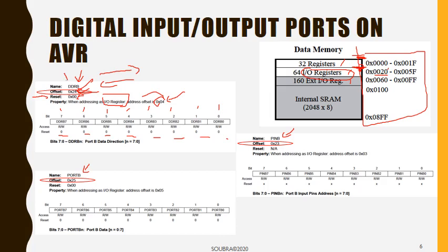So this is true for the direction register, and we're going to find out what value exactly means if we're going to use this particular pin as in or out. But for the time being, let's jump to the PORTB register, and this is where you write the values you want to send outside, inter alia, because it has some other functionality, but for the time being we're going to focus on that. So it's here where we're going to put drive 0, 1, 0, 1, whatever, for each of the physical pins that are set up as outputs.